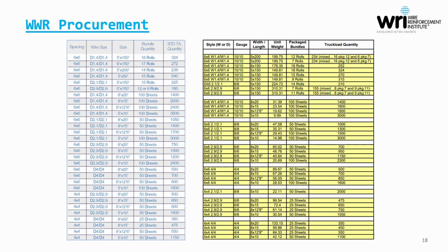Here is just a few snippets from different welded wire reinforcement producers that show the stock sizes, and you can see the 6x6 and the 4x4 patterns, and the fairly small wire sizes that are available that generally describe the stock material. Now, from one producer to the next, the offerings will vary slightly, just based on what their customer demands are. But you can see some commonality here in spacings and wire sizes.